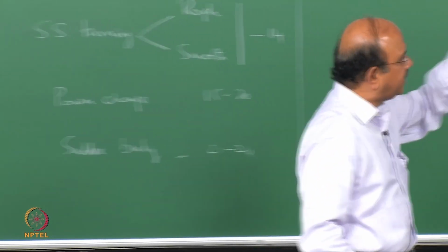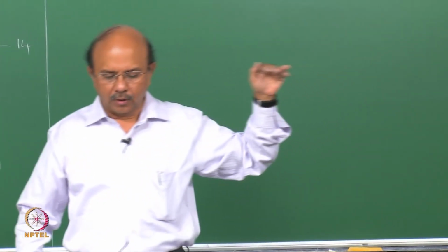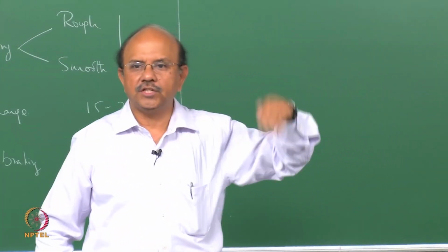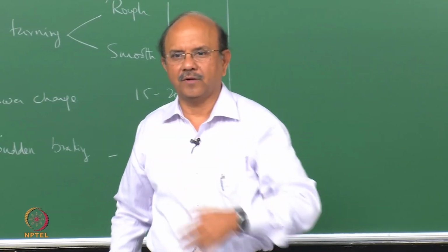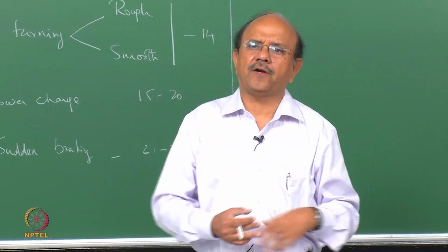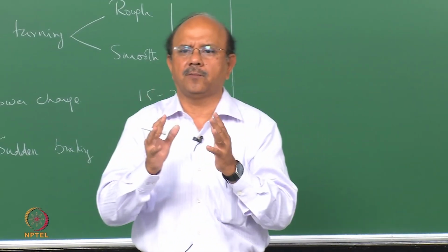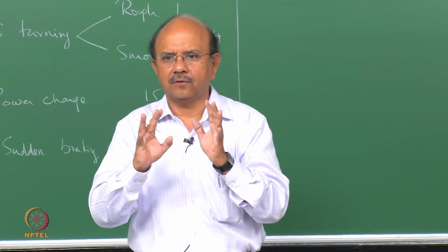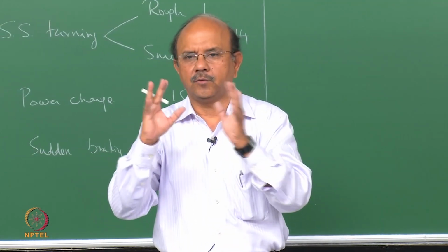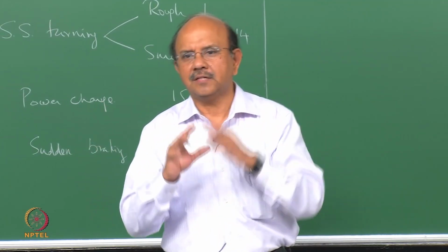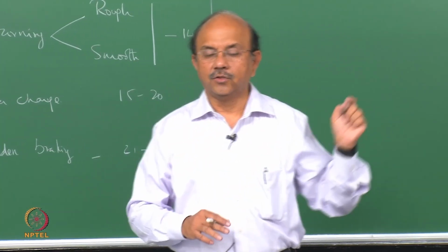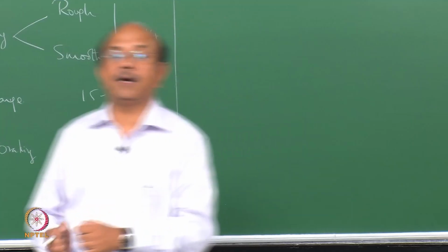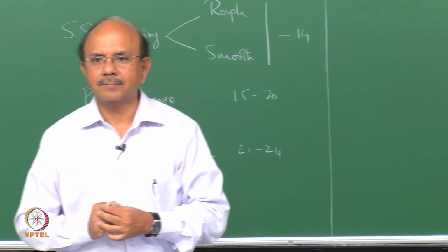Let's say I change damping similarly and so on. I keep changing one by one, and I want to find out each factor. That's one way. But I can't do that because there are so many factors. So we do a factorial experiment to understand the interactions between the driver's feel and these factors, and arrive at a set of values. Clear? So once you arrive at it, you go and start working on your design.